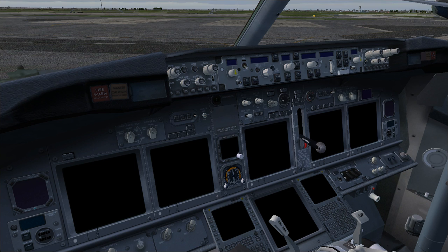The data taken from those systems is clearly varied. We have an inertial reference unit inside the ADIRU, composed of gyroscopes and accelerometers. These platforms can calculate speed and acceleration in every 3D direction, and they can also calculate the position of the aircraft, its speed, the direction and the wind speed.